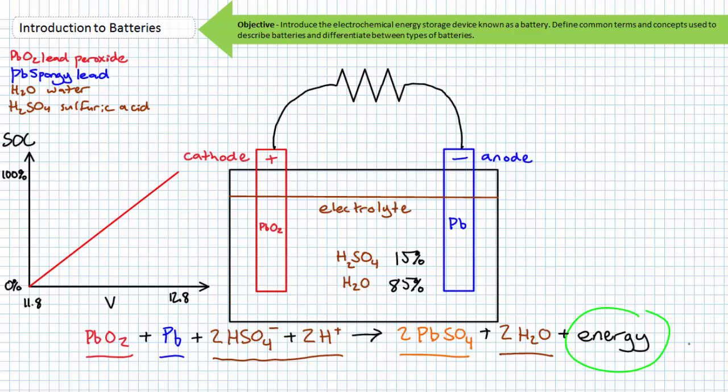We'll discuss the specifics about battery energy capacity measurements in a moment. The state of charge is essentially a quick estimate of how much gas is left in the tank. A nominal 12-volt battery that has an open circuit voltage of 12.6 volts is about 80% full, whereas one that has an open circuit voltage of 12 volts is only about 10% full. Again, this linearity is an approximation only, and at extremes of the range, the linearity fails to hold true. This being said, it's good enough for our purposes, and a lot less messy and substantially more convenient than taking hydrometer readings of the electrolyte.